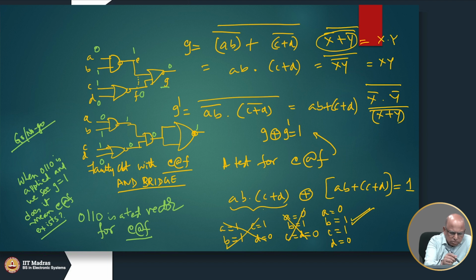So, whatever I just described is known as diagnosis, where we are trying to find the exact cause of the faulty behavior. If we are able to apply several tests and pin it down to a single fault and say, this is a fault which is causing this behavior, then we have resolved the fault.